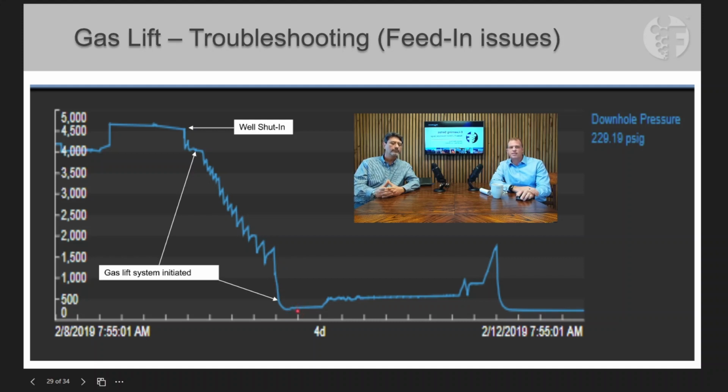In this case, what we found is that we actually had a bridge or a plug preventing formation fluids and pressure from entering the tubing. Basically, the tubing and casing had been completely evacuated of all their fluids, showing that low flow and bottom hole pressure.